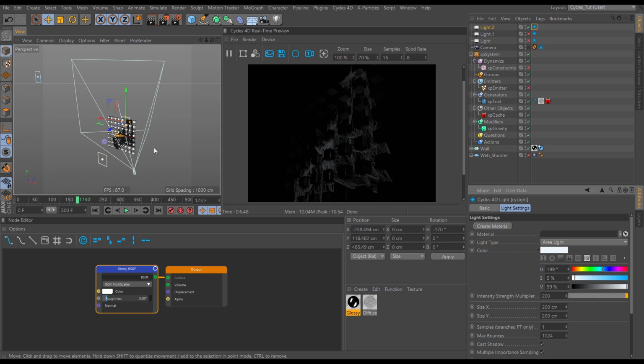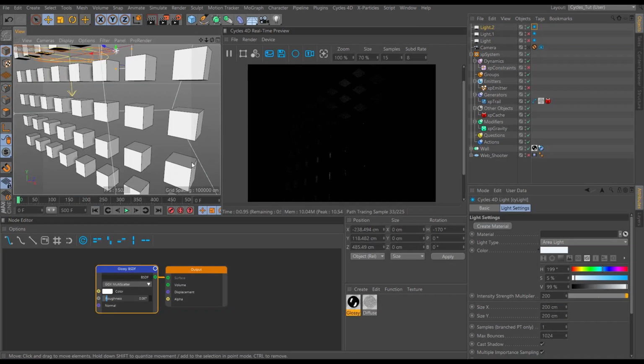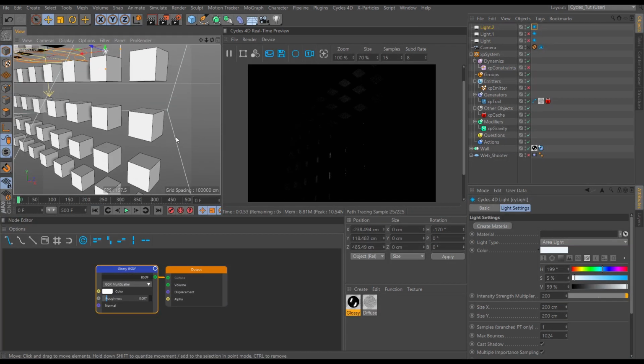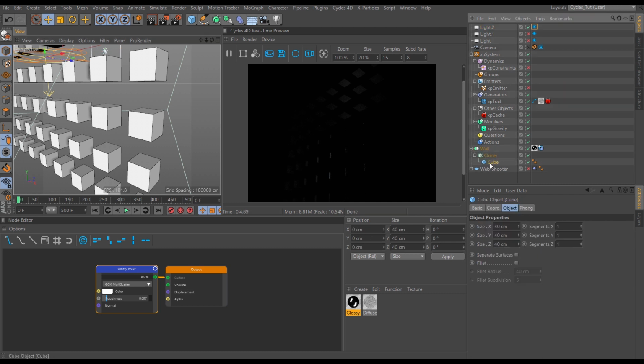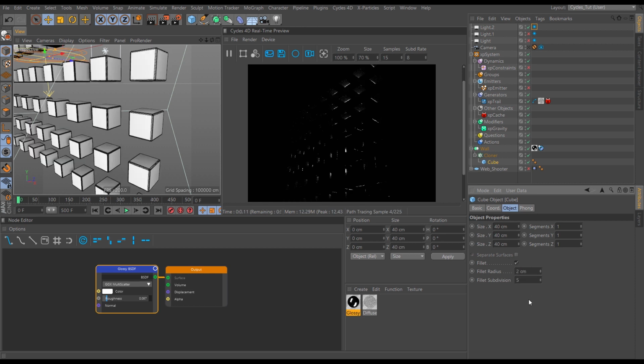So we're not getting much on the corners. And one of the reasons for that is that our cubes have absolutely no bevel whatsoever. So what we could do is a bevel in two different ways. We could go to the original cube that we've cloned and select fillet, which puts, that's way too big, that radius, which puts this fillet edge, gives us a bevel.